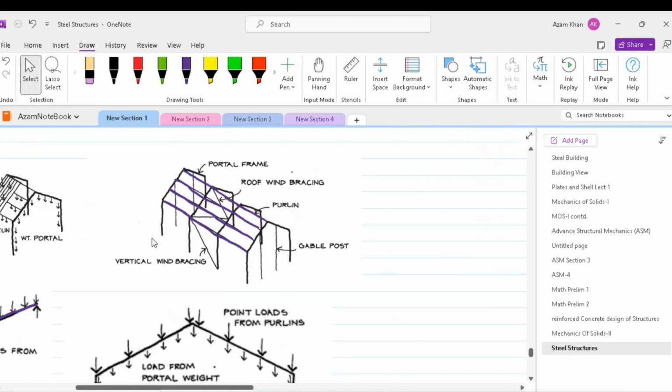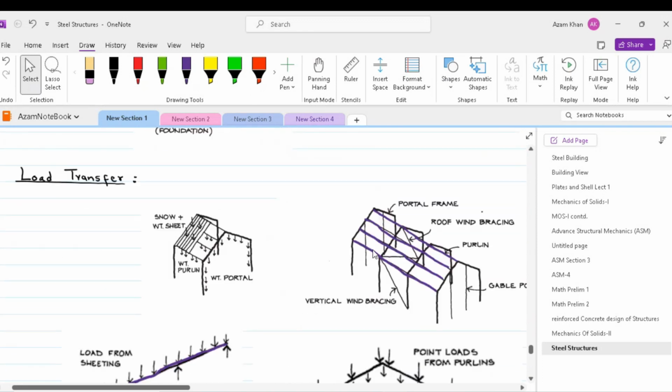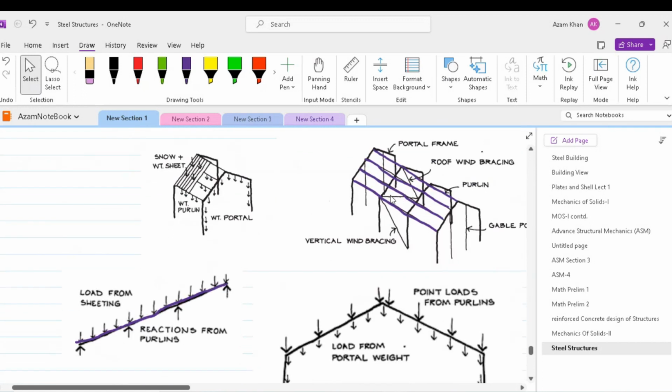Therefore, if the lateral load is in the transverse direction of this 3D building system, that will be distributed among the portal frames after being transmitted by the roof sheeting and the side walls. However, if the load is in the longitudinal direction, the gable frames help to transfer the loads to the braced bay, and the braced bay correspondingly brings the load down to the ground. The braced bay at the roof level is normally called wind bracing.